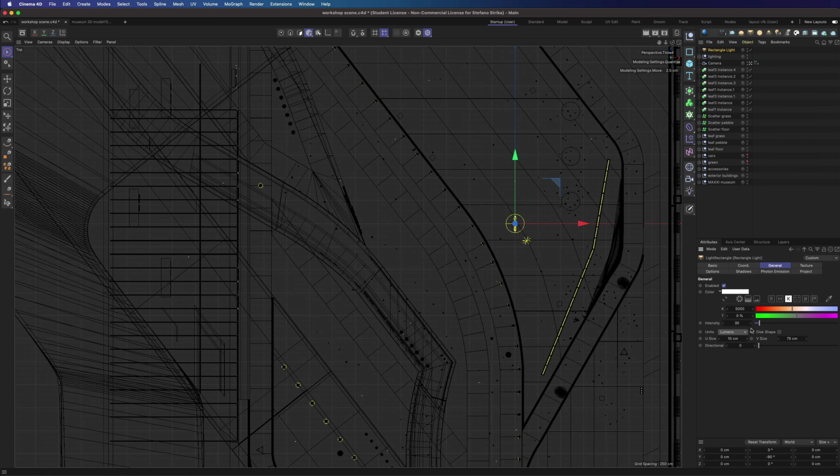Now set the unit to lumens and use about 3500 lumens. And now we can insert the temperature in Kelvin degree. It's not a warm light, so it should be about 4000 Kelvin degree. But I feel that Cinema 4D built-in Kelvin scale is slightly off, so I always prefer to move slightly to higher values. So I will use 5000. Later I will show you how to be more precise regarding the temperature using the frame buffer preset.